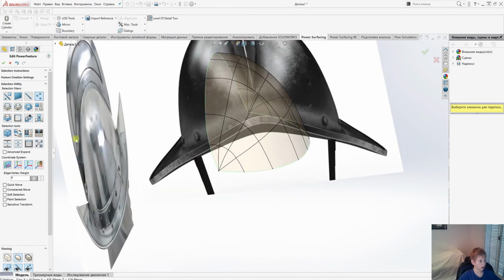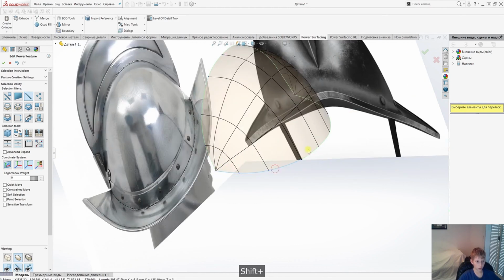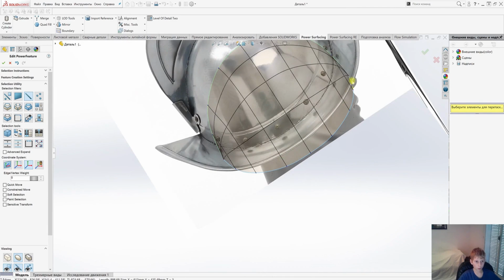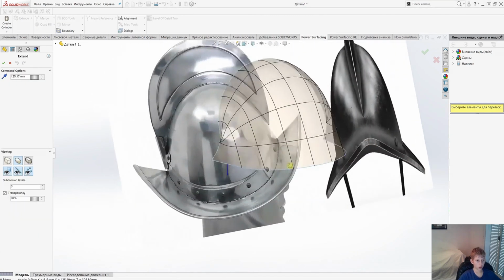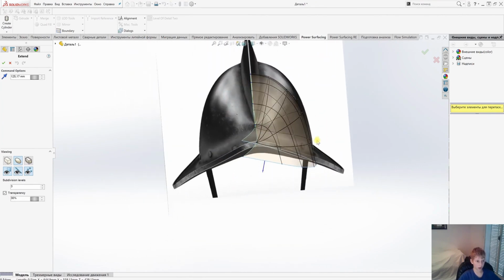To do this, select the edge selection. Edges are the lines, there are horizontal edges and vertical edges. Select our edges. Right click. And now in this step, we're going to extend and extrude our elements downward. They were extruded downward because their vector is pointing down. We'll move them as needed later.